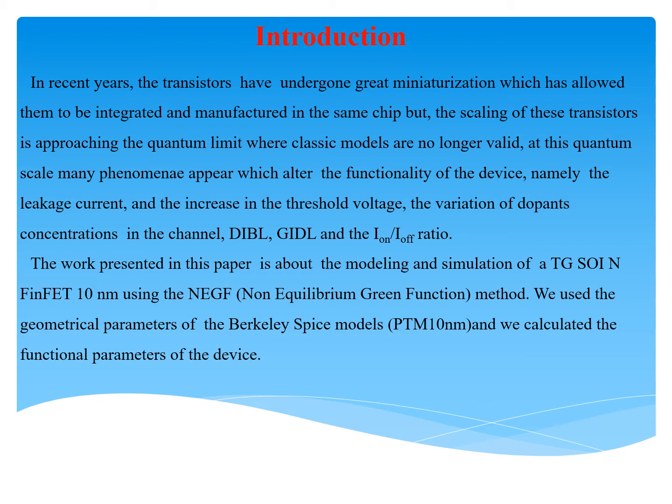using the NEGF, non-equilibrium Green's function method. We use the geometrical parameters of the Berkeley SPICE model PTM 10 nanometer, and we calculated the functional parameters of the device.